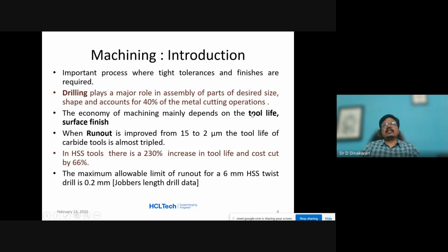These two are the main parameters in machining. Then another thing: if you are not mounting the drill bit properly, it is prone to run out, meaning out of axis. If the system is unbalanced, what kind of behavior will you have? It's a kind of wobbling motion you can observe in the machine. So these are the three problems.